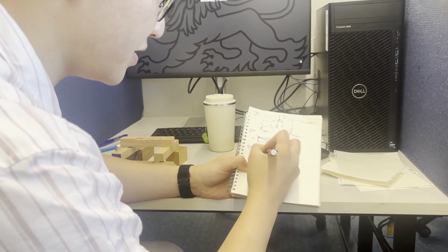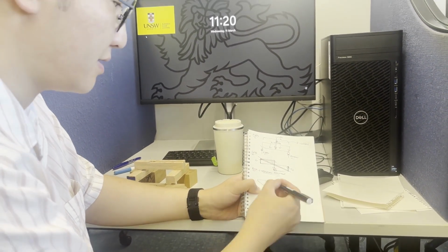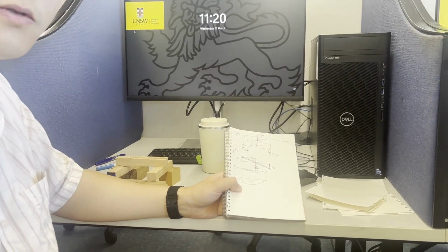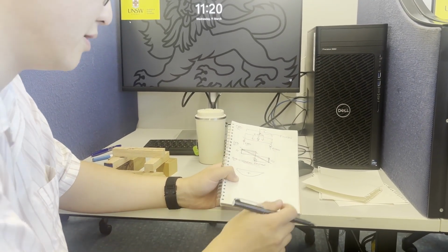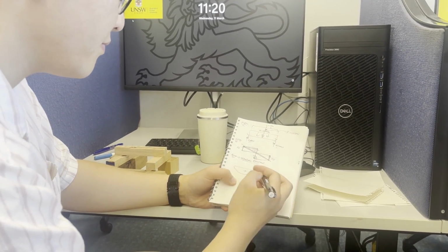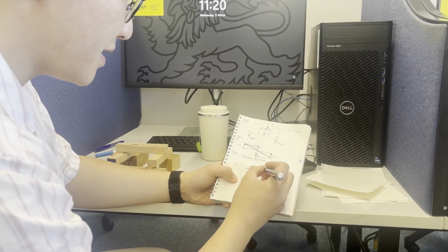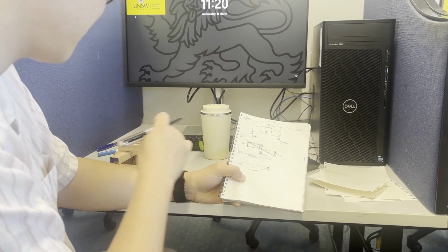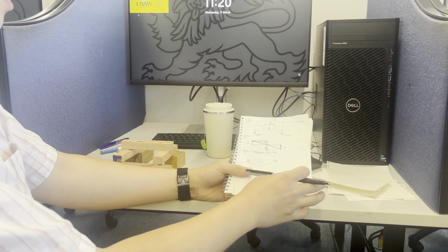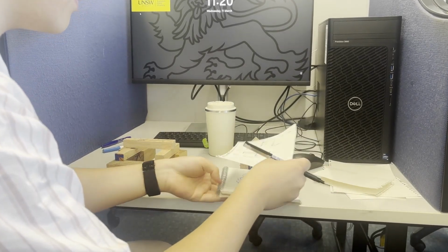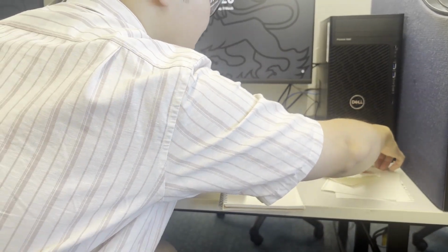Okay, that's tension positive convention. So the tension side is the bottom side of the beam, and it's going down. So that's what the bending moment diagram looks like for that secondary beam. Now the interesting thing that I didn't realize when I was an undergrad